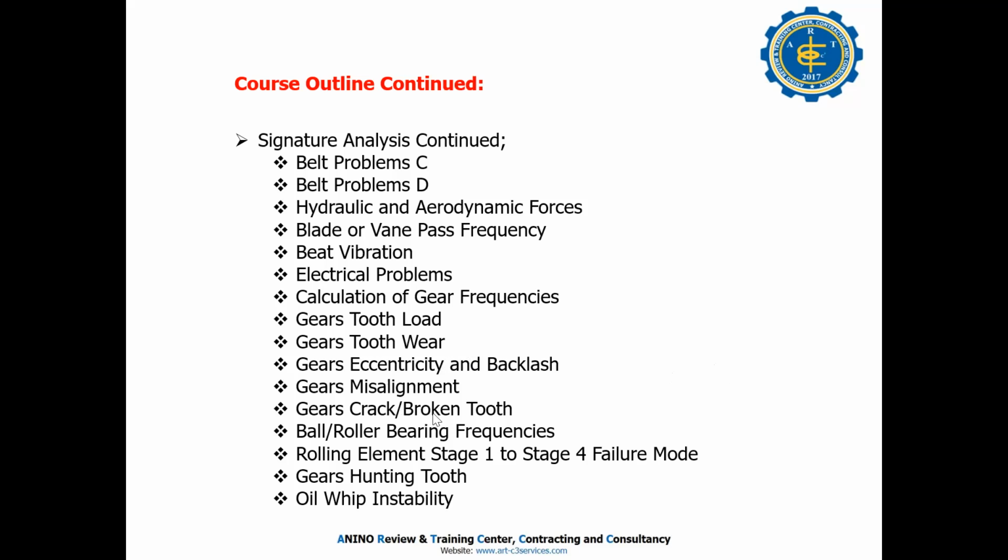If you have a gear crack or broken tooth, in my experience the bearing frequencies are dominant. You can see the broken tooth only if it's already there; if there is a broken tooth, the motor will trip because it's hard to drive.